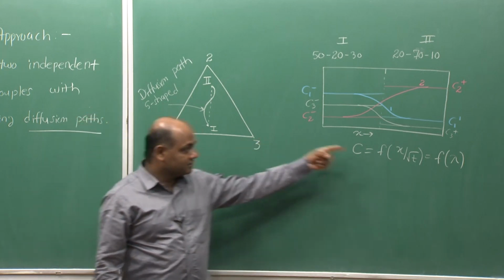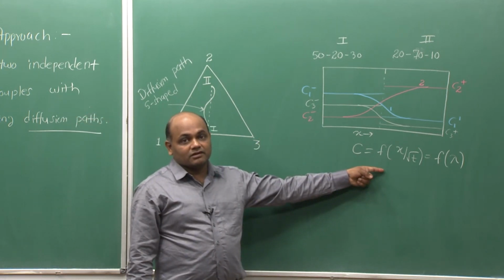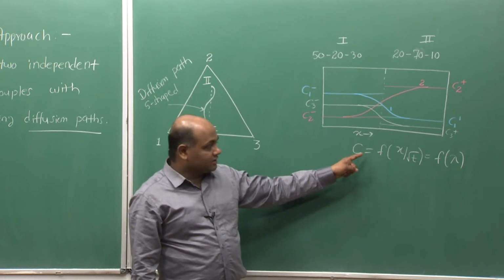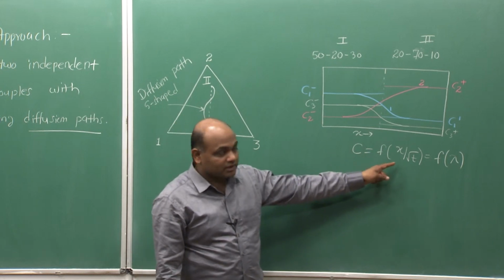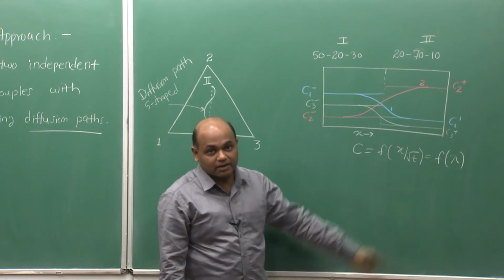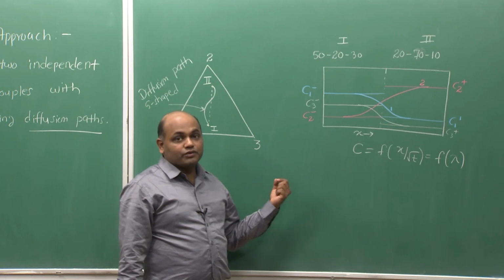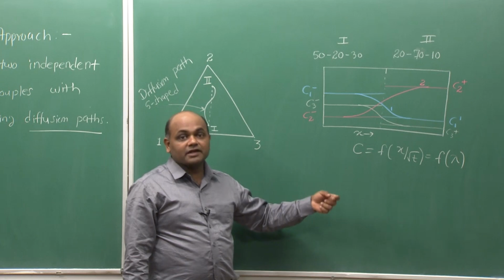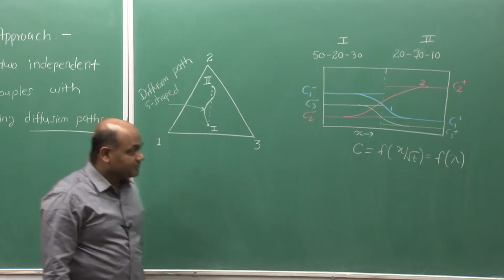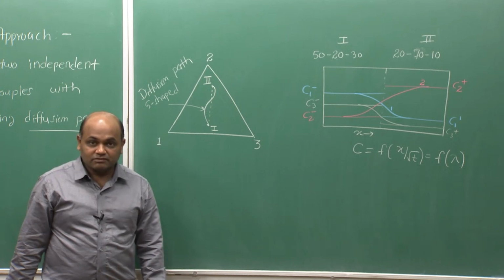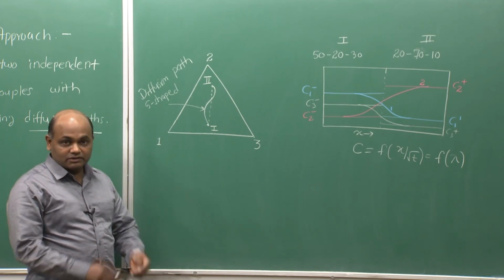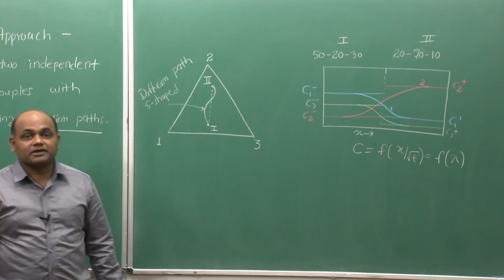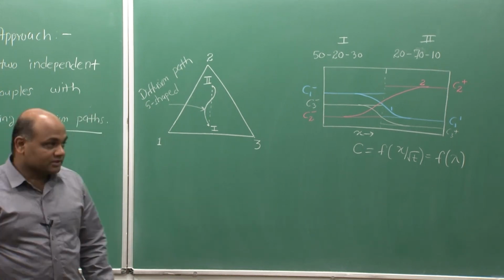And this is because in an infinite diffusion couple, each composition plane moves parabolically with time. It is a function of the Boltzmann parameter lambda. There is no new composition plane added or any composition plane getting removed, and so obviously the sequence of compositions will not change, although the profiles will broaden with time. So the diffusion path is independent of time, and this is an important concept.